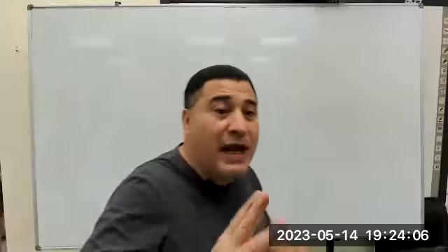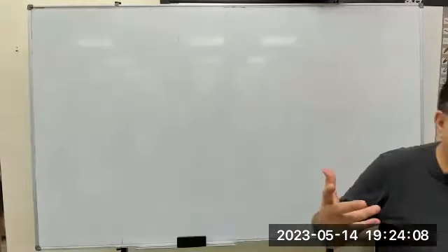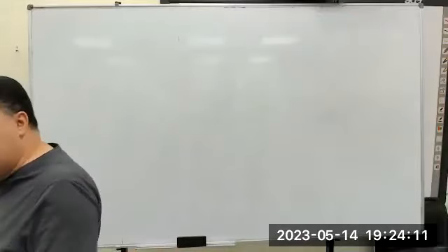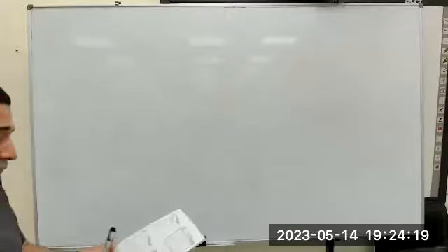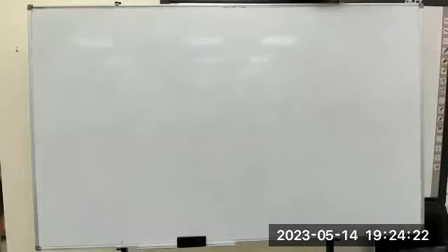From the first impression, are these slabs two way? Without dimension, let us have our sense. Let us use our sense, guys. Are these slabs in one way or two way? Is this one way? All of them one way. The 4 slabs in A, one way. Slabs B, one way. C and D. 100%, D is one way slab. Why? Same as our slab here. But the C, no, C looks like equal 1.